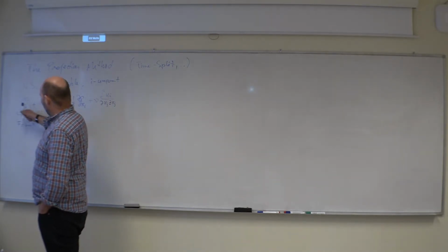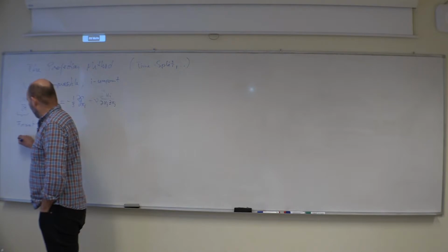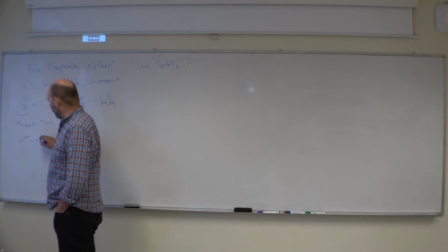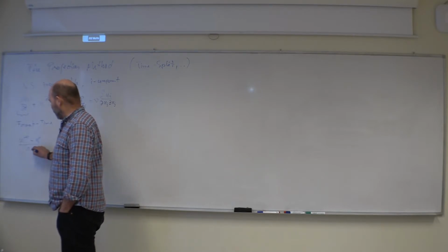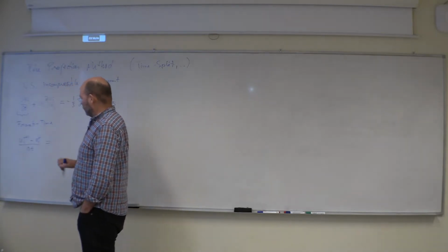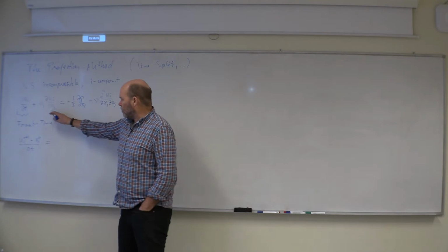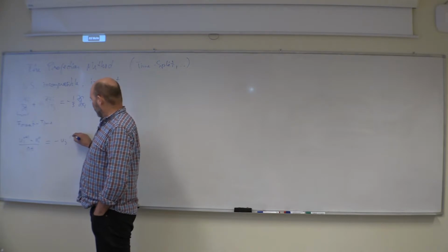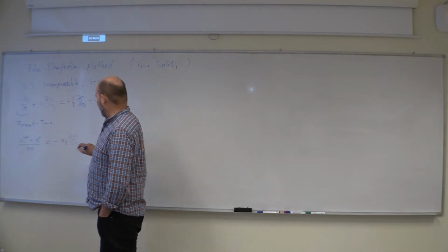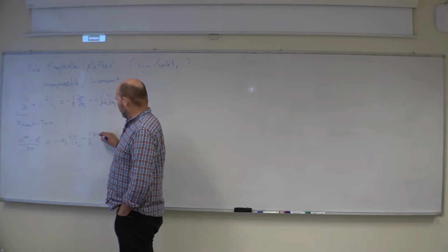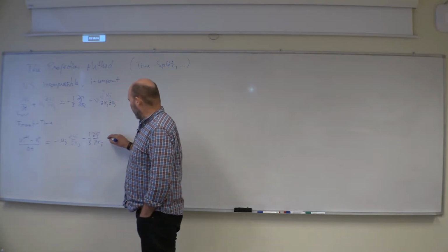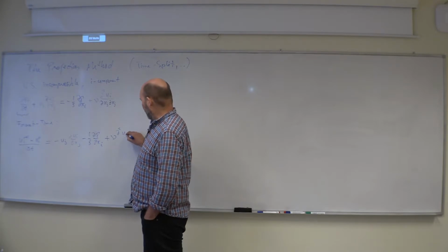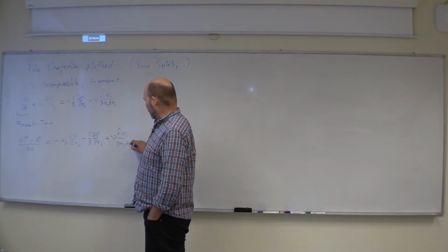What do we have? This one now I will write as u_i^(n+1) minus u_i at time level n, divided by delta t, equals, I throw the convective terms on the other side, so they will then become negative u_j du_i/dx_j, the pressure dp/dx_i, and then kinematic viscosity, double derivative of u_i, dx_j dx_j.